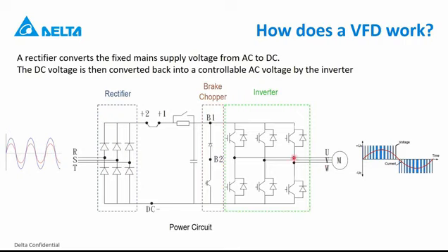Now, the sequence in which the IGBTs of the drive open will determine the frequency that the motor sees, and the duration, so how long the IGBTs are open, the duty cycle, will determine the voltage that the motor sees.